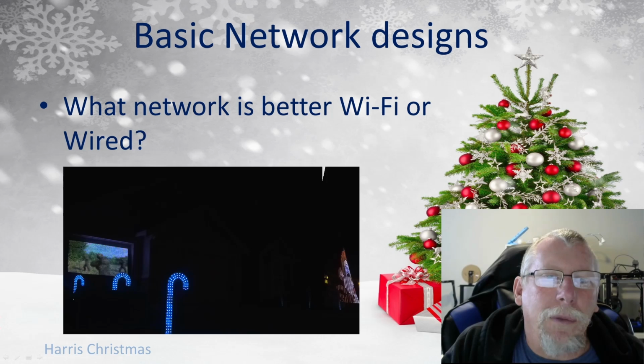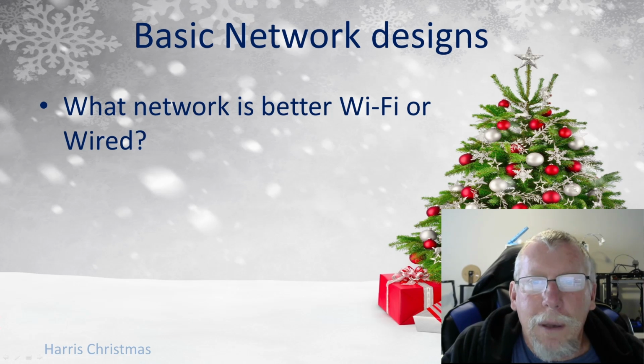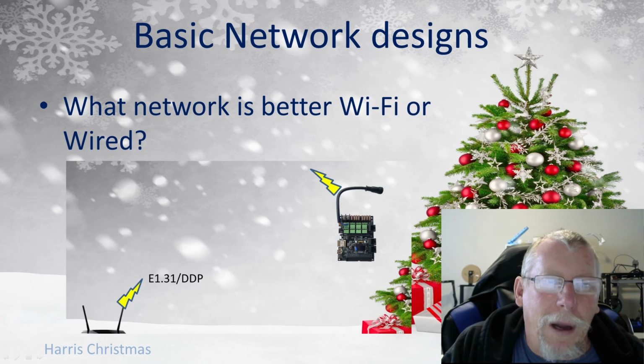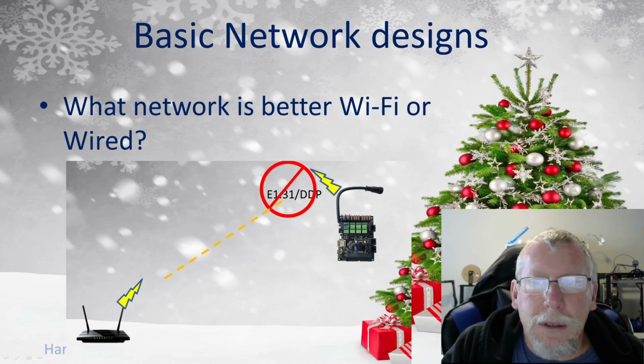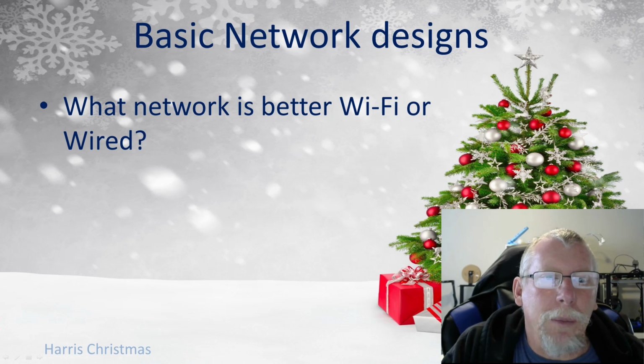Both methods work very well when properly configured, but both can have failures. One thing to note is using Wi-Fi to send E131 or DDP data can be problematic. But there's a method called multisync. This used to be called the master remote mode. And this is designed to use multiple controllers that communicate via Wi-Fi, and it works very well.